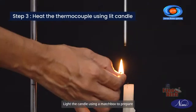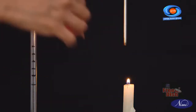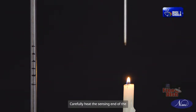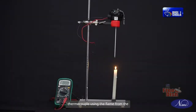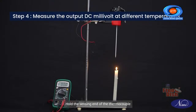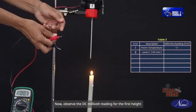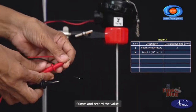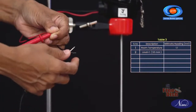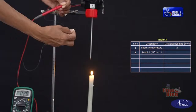Light the candle using a matchbox to prepare for heating. Carefully heat the sensing end of the thermocouple using the flame from the candle. Hold the sensing end of the thermocouple near the flame for 5 to 10 seconds. Now observe the DC millivolt reading for the first height, 50 mm, and record the value. This initial reading serves as a reference point for comparison.